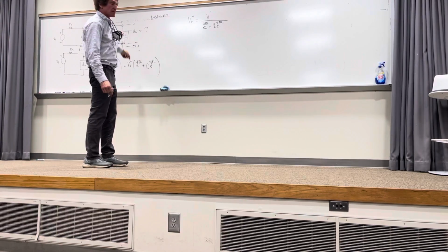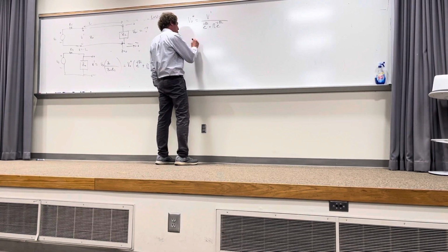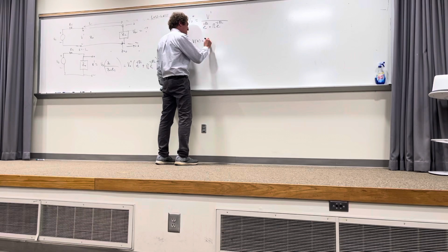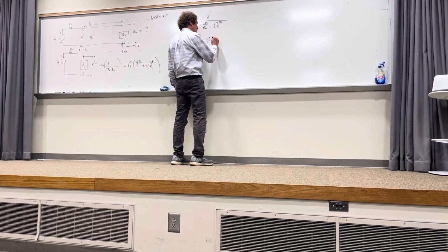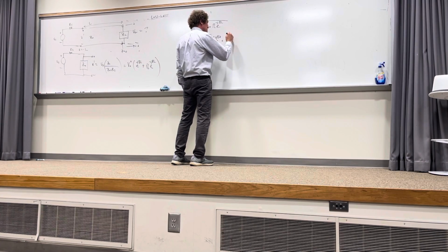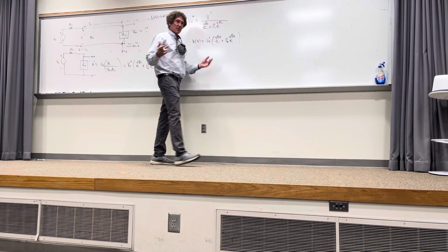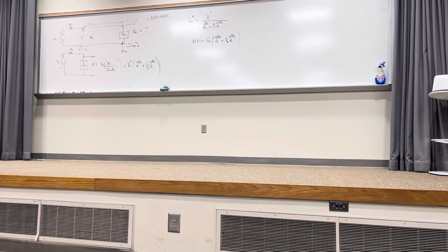So now that I have that, why would I want that? Remember, the goal was to find the voltage at the load. Well, I know that the voltage anywhere is equal to V0 plus times E to the minus J beta Z plus the reflection coefficient times E to the plus J beta Z. That's what it is anywhere. Do y'all agree? We've got V0 plus, correct, class? That will be a magnitude at an angle. It will not be just strictly real. Remember that.